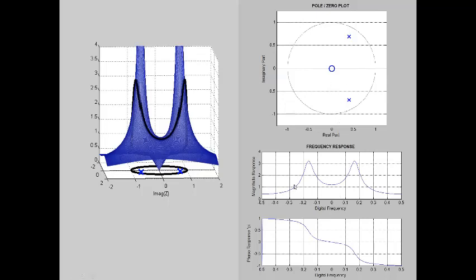If we want to create something like a bandpass filter, if we want to accentuate a certain range of frequencies, we can push those poles out a little bit further. If it's not at DC or at the Nyquist or at f equals a quarter, if it's some other value, we're going to need 2 poles. We're going to need complex conjugates to do that. We'll see why in a moment. But what's happening is as we come around the unit circle, as we come around at higher and higher frequencies, we're getting closer and closer to this pole. We're coming around looking at the projection, then we're getting closer and closer to where the rubber sheet's getting pushed up. And we're kind of riding a little roller coaster here as we go by the pole.